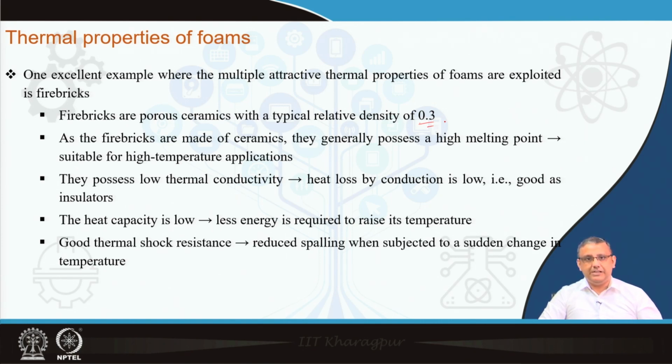possess low conductivity and high insulation properties. Also, fire bricks are made of ceramics, and as we know, ceramics have a high melting point and are very protective at high temperatures, and that also renders fire bricks applicable to high temperatures. Fire bricks also possess low conductivity. As we already learned, they have a high amount of porosity, and this renders the material low in conductivity, which also makes them very good insulation material.